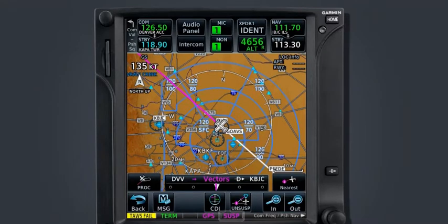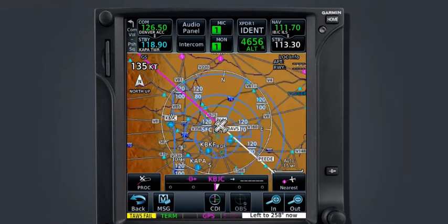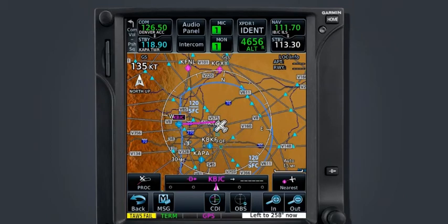In addition, an Unsuspend button is placed on the button bar on the map page to the left of the In and Out range buttons. Selecting the Unsuspend key will create a direct-to-flight path to the destination airport. Another way to resume waypoint sequencing would be to activate an approach to the destination airport. This will be covered in the next lesson.